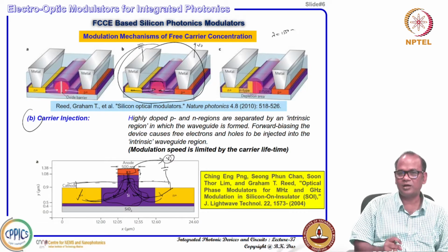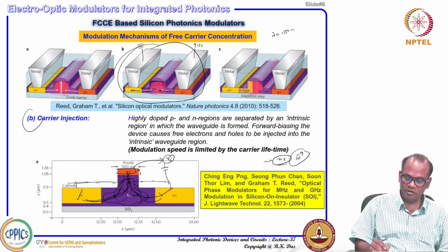For a given semiconductor, if you have a certain carrier density for electrons and holes, you can create excess carriers. Once generated, they will try to recombine, and it will take its own sweet time, in the order of, say, nanoseconds, 10 to the power minus 9 or so.